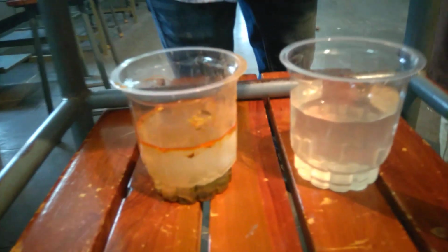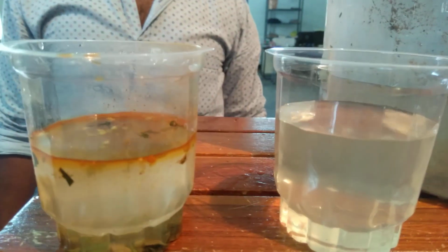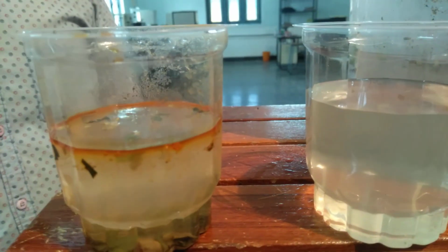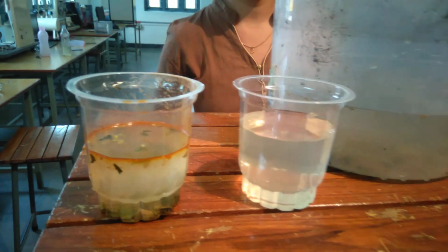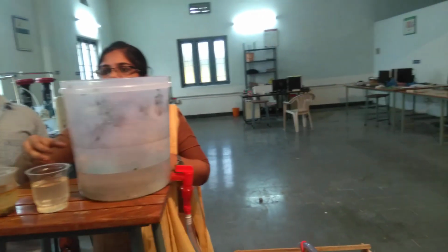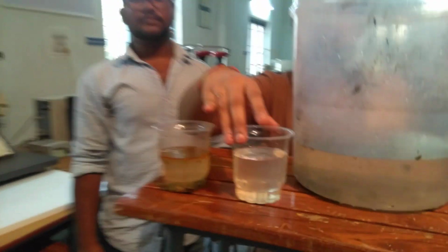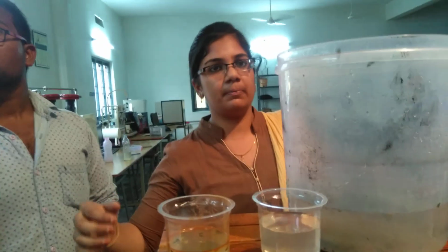You can see the comparison of the initial water which we have taken from the village and the filtered water which we got after the filtration process. So you can clearly visualize how much difference there is between the treatment plant water and the initial water. And the TDS is expected to be less than 250 after the filtration process. So we are using this filtered water for the irrigation purpose.